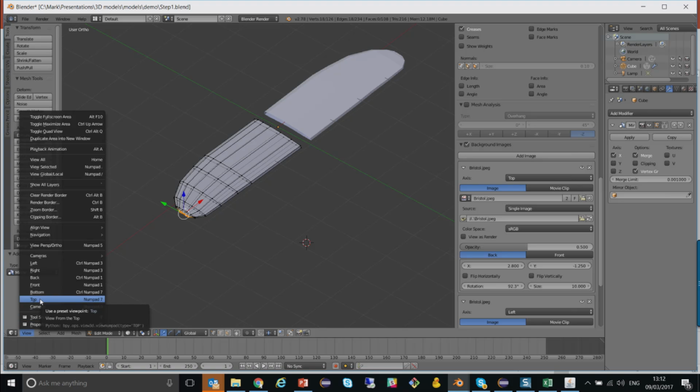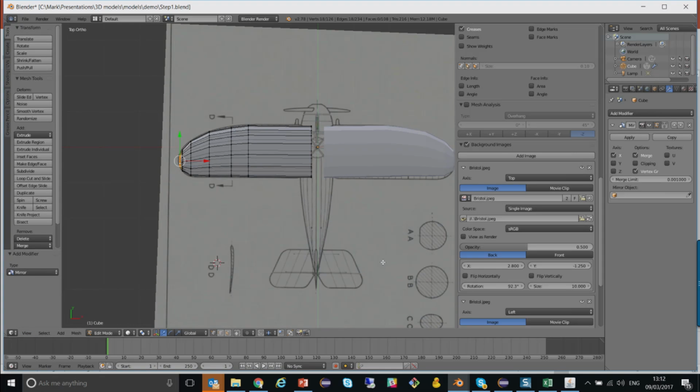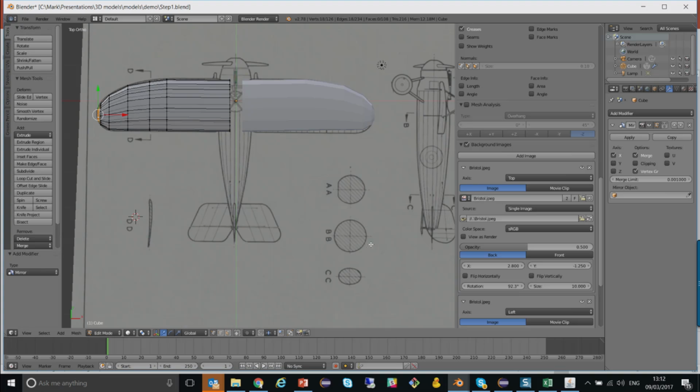What about a bit of fuselage? So what I'm going to do is I'm just going to draw now a circle around the BB section of the aircraft. So all I need to do is add, and I'm going to create myself a circle, and just dragging these axes here, I can centre that on the BB cross-section of the aircraft. So I'm going to press the S button now, and I'm just going to scale that down so that it's roughly correct for the bit of the fuselage that I'm drawing.